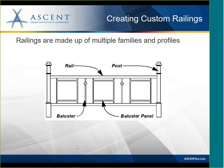So railings are made up of, like I said, multiple families and profiles. All of these families and profiles need to be in the project you're working on before you create the railing, and I'll show you a lot about that in just a few minutes. What we've got are posts, so here's a post on the end. We've got rails. Rails are horizontal items, and we'll talk a lot about rails because there's a lot happening. Balusters, like this one here, are our vertical items, and you can also have baluster panels, such as this one here in the center, that is really just a wider baluster.